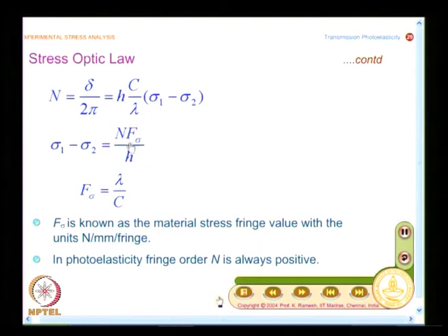But even before we discuss these issues, let us have a look at what photoelasticity can give. See, I said photoelasticity can give you directly only the fringe order and the principal stress direction. How it is going to give, how we have to do it, we have to look at the optical arrangement, understand, and then go about it.